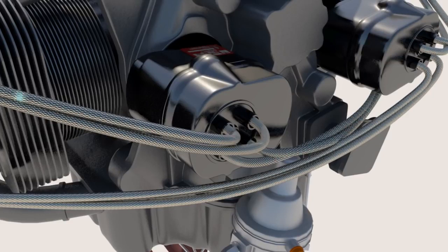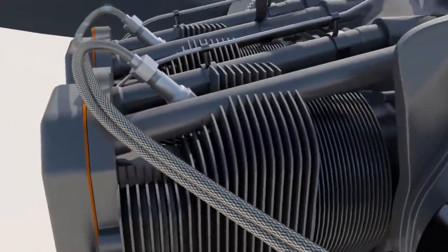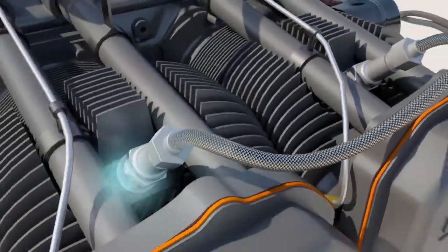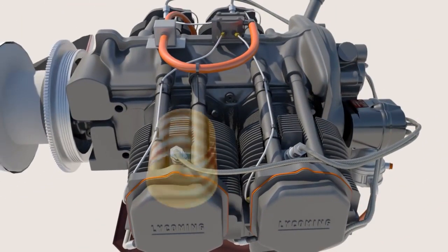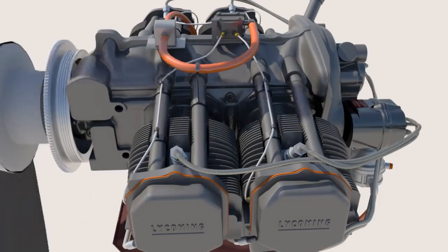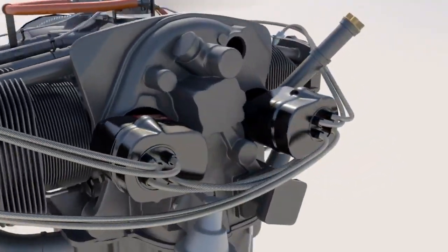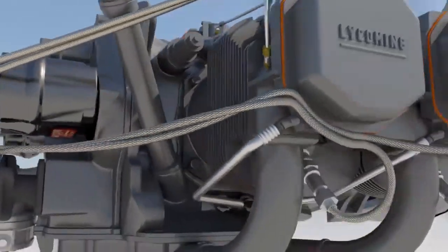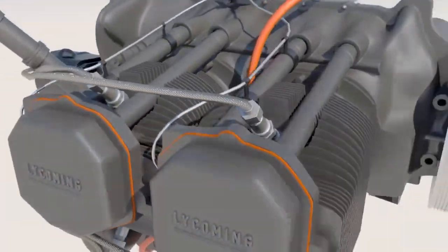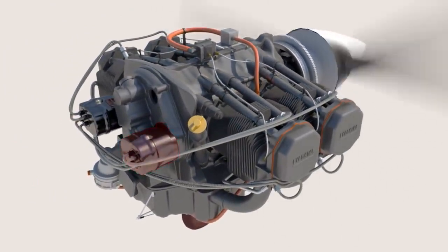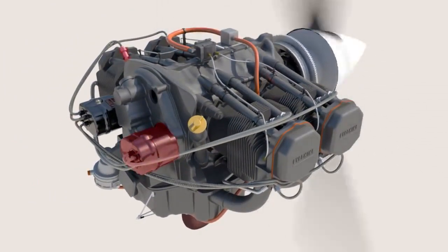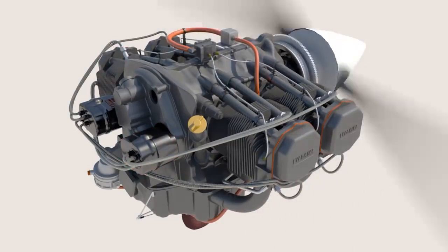The energy generated from the magnetos is sent to the spark plugs. The spark plugs then release that energy, which ignites the fuel-air mixture, creating power to turn the propeller. Most airplanes have 2 magnetos, multiple sets of wires, and 2 spark plugs per cylinder in order to increase efficiency and reliability of the system. If one magneto fails or one spark plug fails, the engine will still run. However, power output will be slightly reduced as the engine is operating less efficiently.